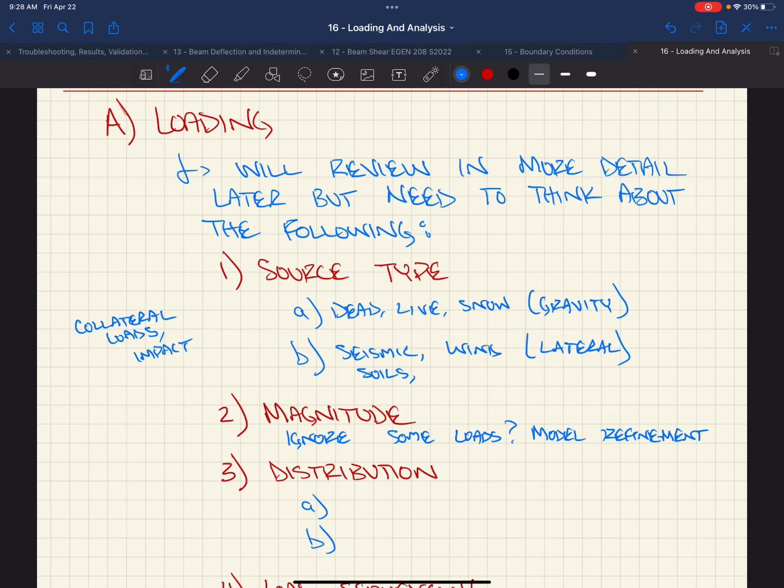But if you were designing a weld, like a plate that was welded against another plate, and this plate had moment and shear on it, the weld you design is going to have both the moment, the T and C forces in the weld, plus the shear forces in the weld, and they interact. It would be very conservative to find the maximum shear from one combination and the maximum moment from another, and design this connection for both of those magnitudes.